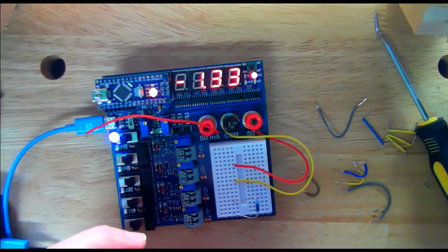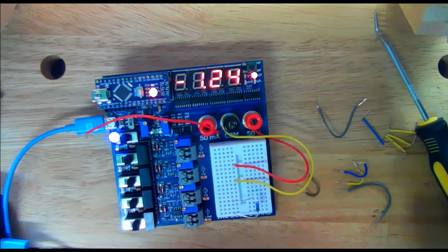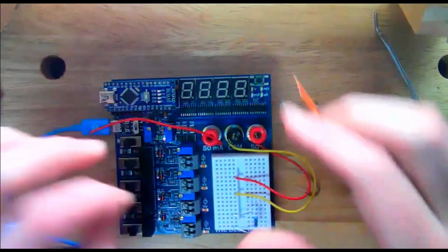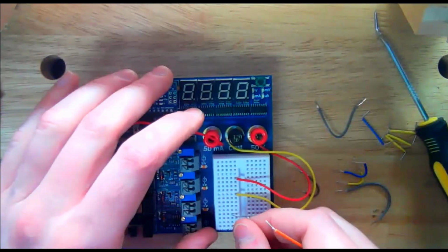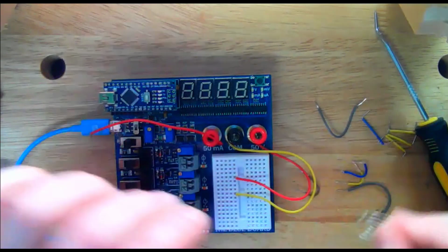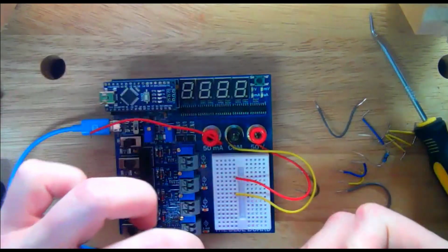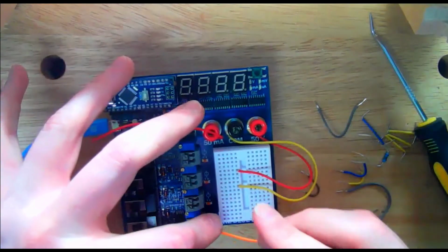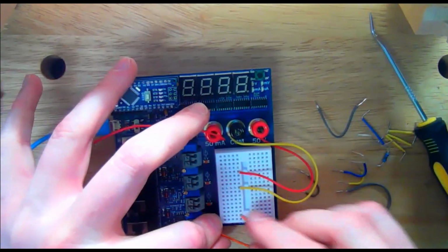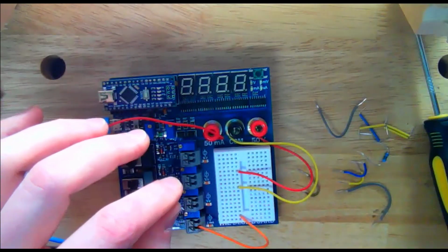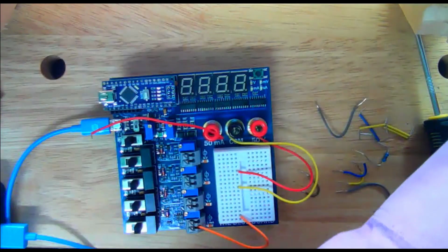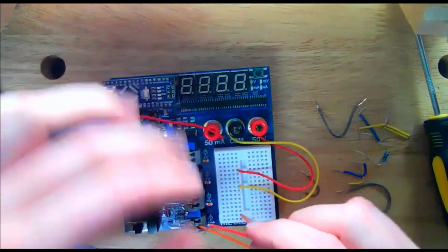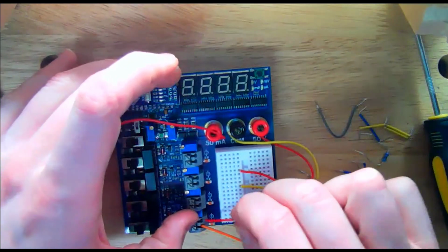Okay, so let's use a color wire that you're actually able to see. Let's do the current supply. It might not be able to do a 1K resistor, so let's just short the current supply. It's okay to short a current supply. Current supplies are perfectly happy being shorted because it's very easy for a current supply to drive a short circuit. There's nothing to impede the current that it's trying to produce.